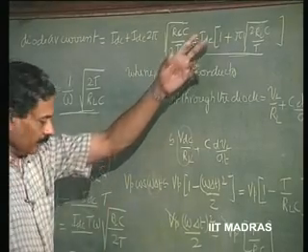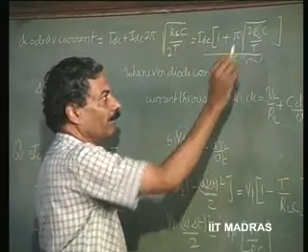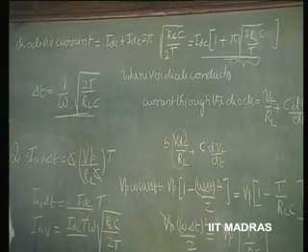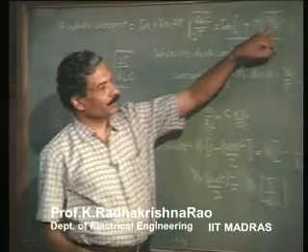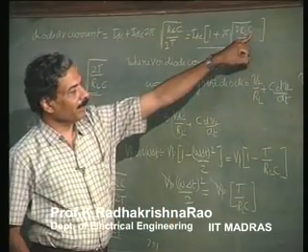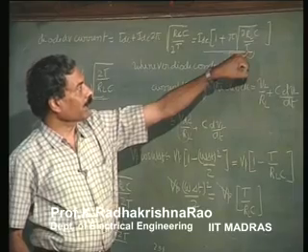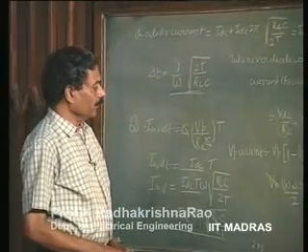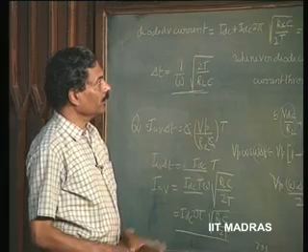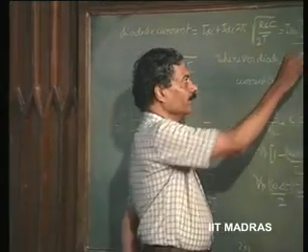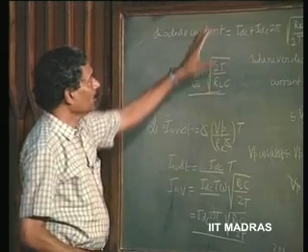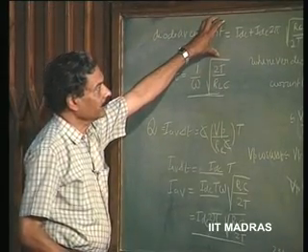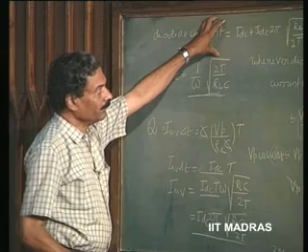So, this factor, if you evaluate for this problem, it will be very nearly about 23.1. Please try to evaluate taking all the values of R L, which is 1.2 K, C is 192.3 microfarad and T is 20 milliseconds. So, it comes out to be very nearly much greater than this I d c. I would like you to evaluate this, and this is the one which normally fixes up the value of the peak repetitive average current. So, please work this out.